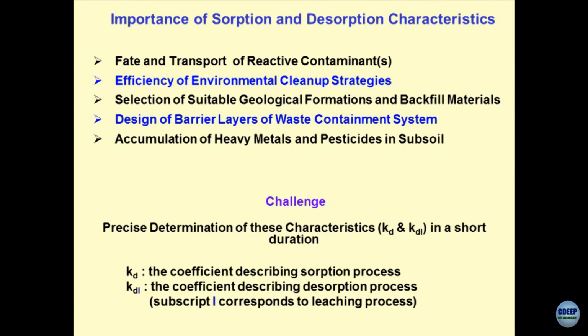Imagine, see, this is the beauty of these sentences, that their implications are so tremendous. So, you have a landfill and surround the entire landfill with some curtains which are not cutting off the seepage only, but they are reactive also. So, curtains which were done by grouting were only stopping the seepage, clear? Now, what you have done in the form of reactive barriers, you are treating the contaminant and stopping their movement outside in the geo environment.